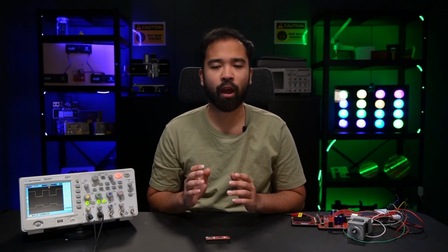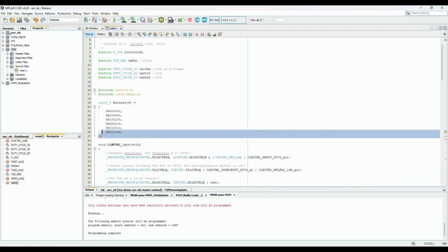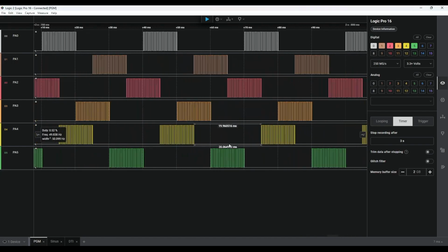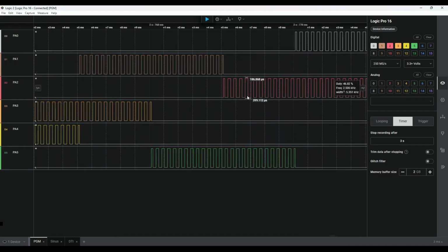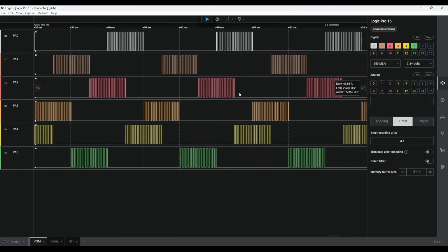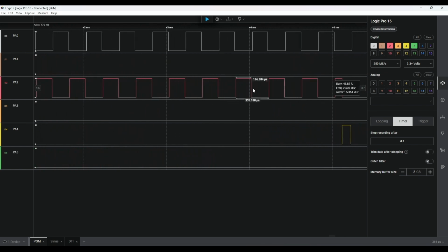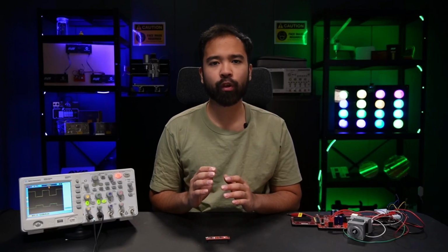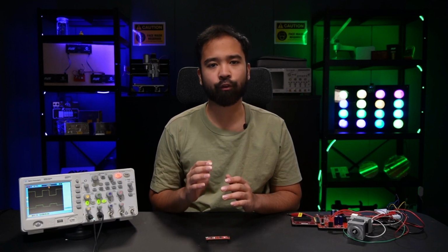The waveform extension also has a mode called pattern generation mode. In this mode, the user is allowed to override the output pins of the waveform extension. Therefore, the user can override a single pin into either high state or low state, while other signals can continue. This mode is very useful if you want to make specific patterns. For example, if you want to spin a BLDC in a 6-step commutation, you can make those individual steps in this pattern generation mode.